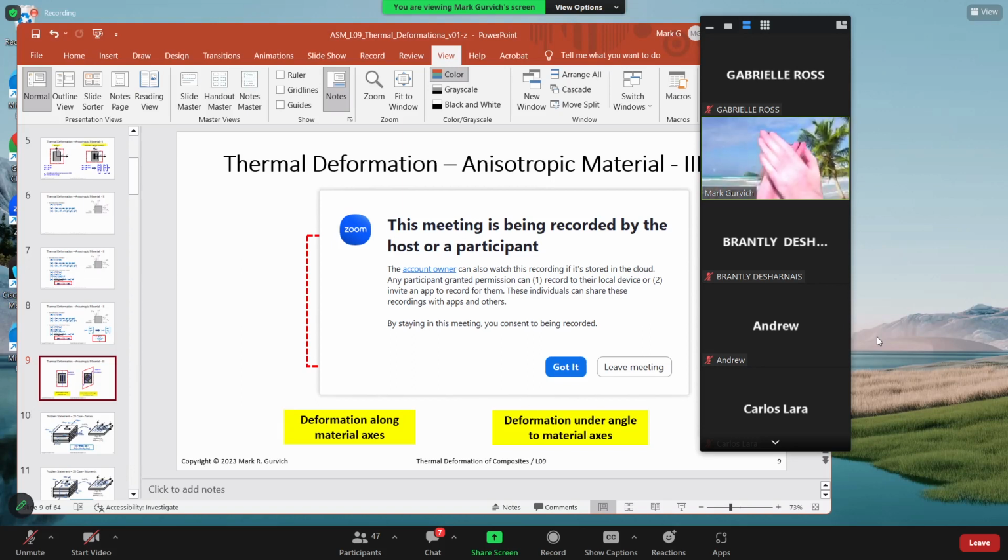So again, now imagine you have a system plus alpha minus alpha. You heat it. One layer tries to rotate in one orientation, another tries to rotate in the opposite orientation. They have to deform together because it is the same system. And as a result, now we have a huge shear between them.